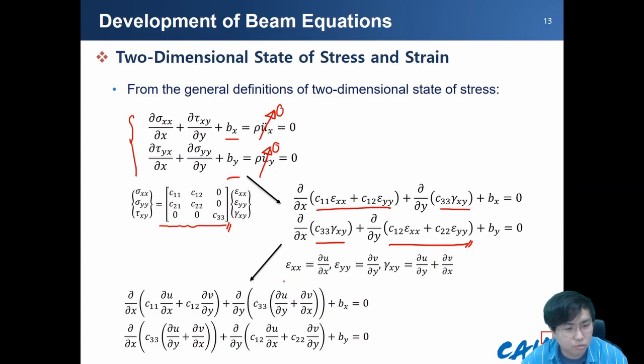And here we are going to change the strain into a derivative of the displacement field, and it looks like this. We are going to have some slight issues with the shear strain. However, in this lecture, please just follow these concepts. Epsilon xx can be changed to du/dx, and epsilon yy to dv/dy. Similarly, the shear strain is du/dy plus dv/dx, a summation of both terms, and it looks like this. This is the general concept.